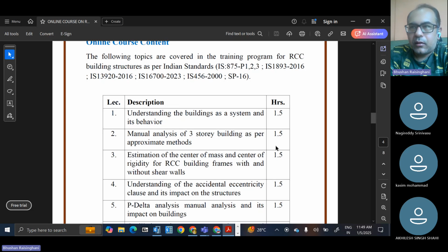But when we go to 3D modeling and 3D software, there is also a twist that the column has to take. So what I think is, when we consider the actual forces on the column and then give a final product, it should match with the software, because all forces in both directions, MU1, MU2, then the twist and the axial force, if all are considered properly, the strain analysis should give us the result. That is the reason we should know how these formulas of SP16 have developed.